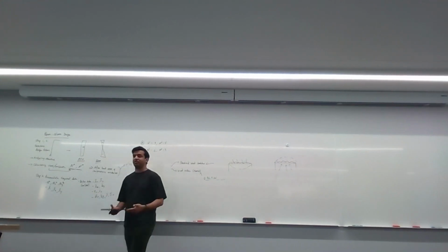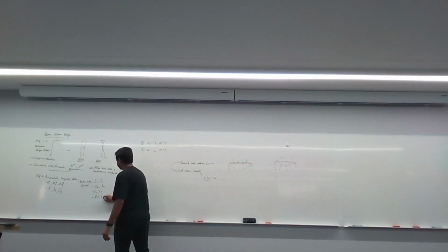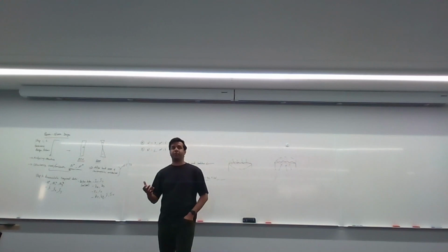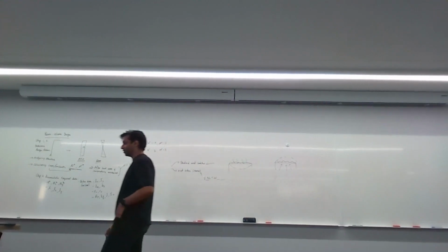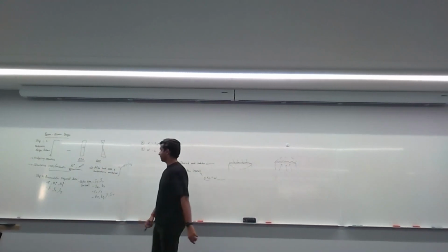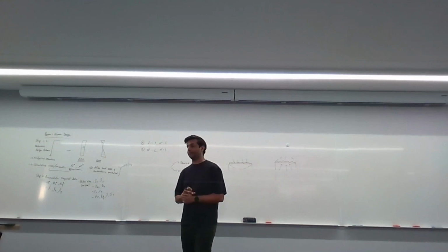So remember, An is your net cross-section area, kf is your form factor, and J is your polar moment of inertia. Iw again has to do with twist. Okay, it's like all based on warping. Okay, so those are all the section data that you've got to take out.